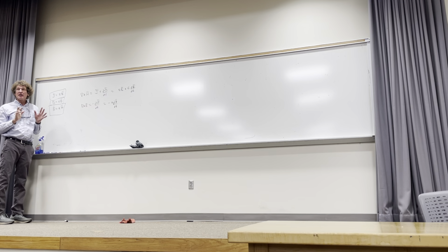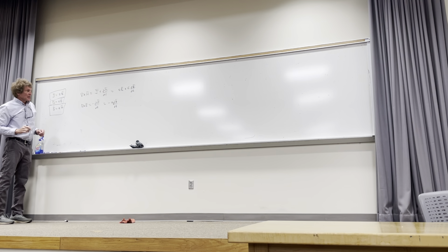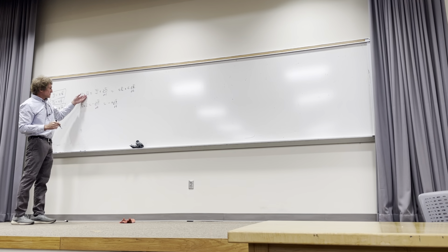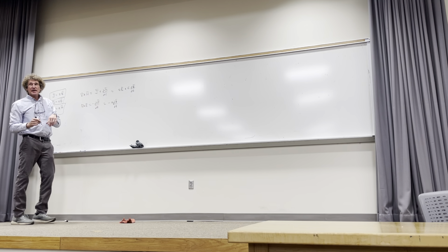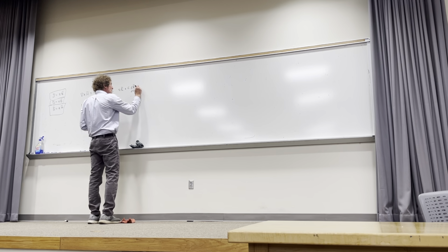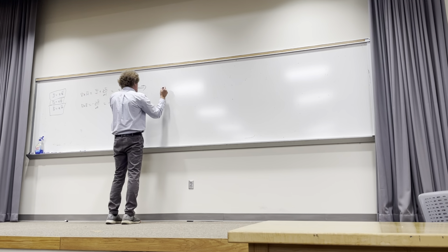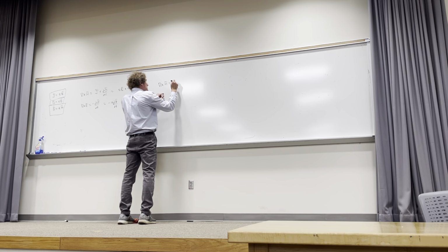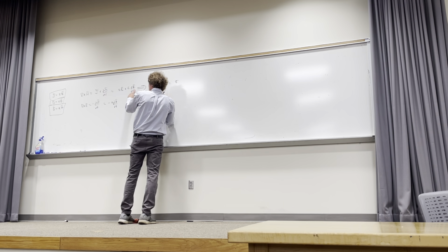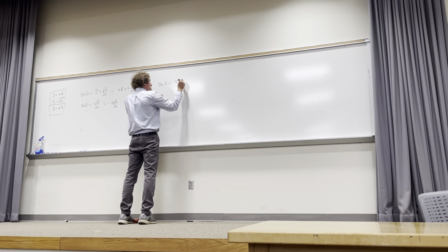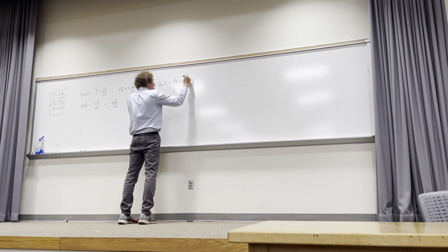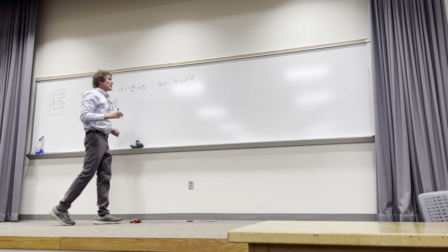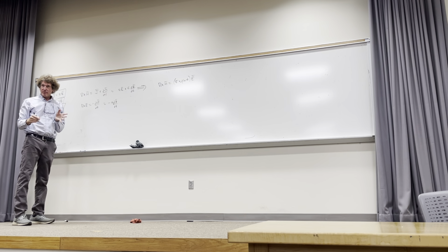All right, it's important to understand. The reason I'm doing this is I'm trying to reduce the complexity. I'm working my way towards something that's manageable. Now, when I have these two equations right here, I'm going to take everything to the frequency domain. So the first equation here becomes curl of H is equal to, now remember, I got a sigma here, but every time there's a time derivative, I bring out a j omega. So it's sigma plus j omega epsilon times E. Y'all follow me? How come that happened, everyone?